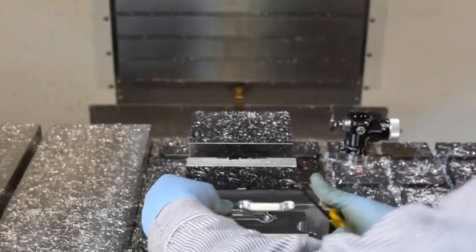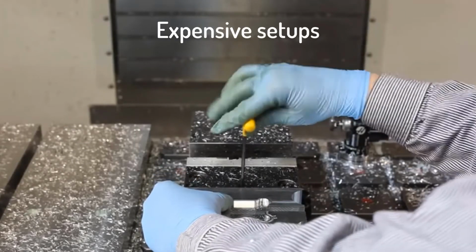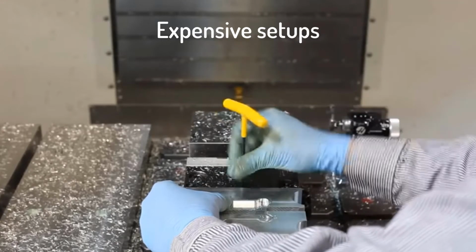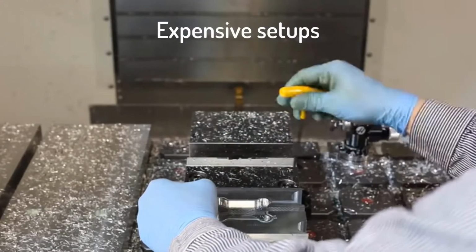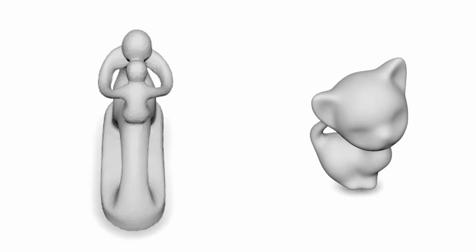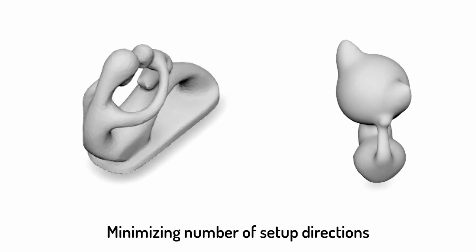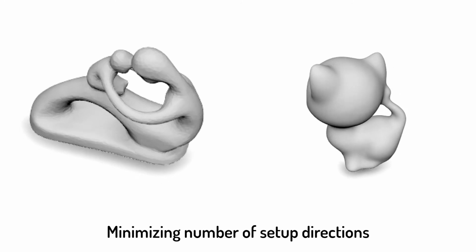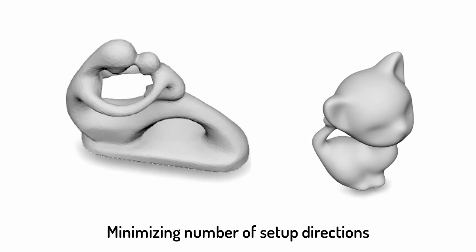In practice, machining experts must plan the machining process by avoiding unnecessary shape setups on the operating table and repositioning the cutter on the shape, since each setup is an expensive and delicate process. Finding a minimum number of setup directions is highly challenging for humans, especially when the target 3D object is freeform and geometrically complex, such as the fertility.